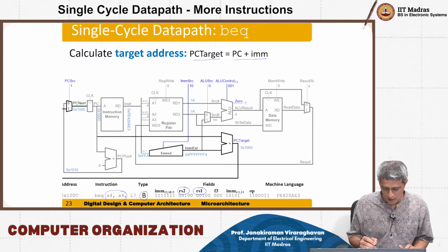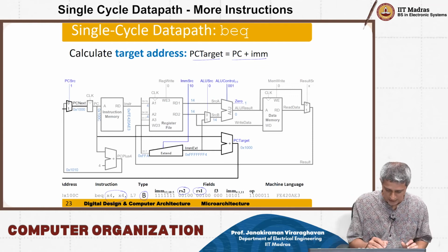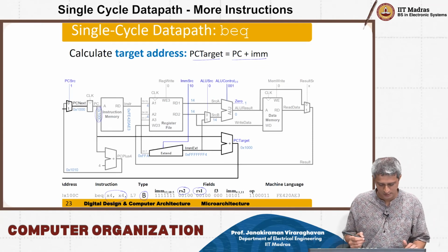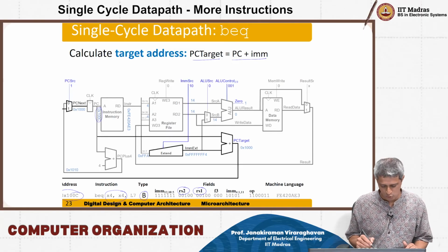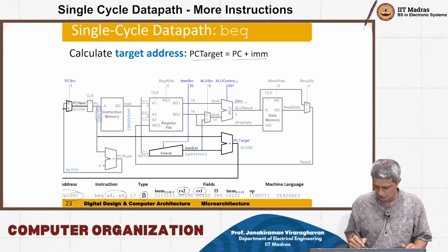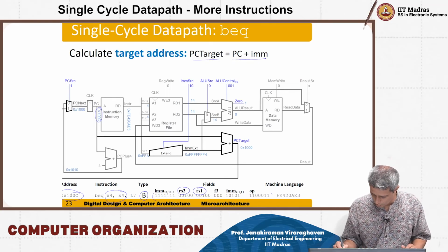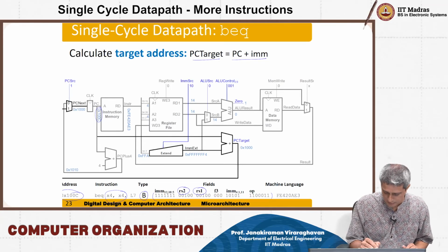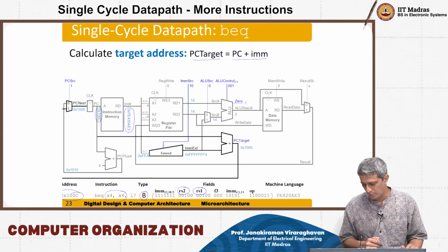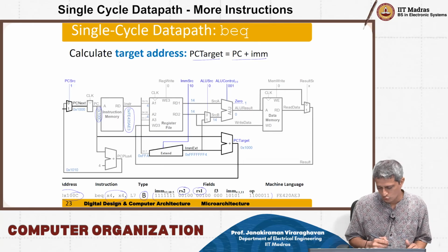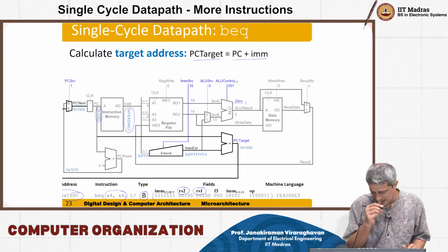So what you are doing here now is, at 0x100C, you have this branch on equal instruction, which is this opcode here, and that has been fetched from your instruction memory: FE420AE3.